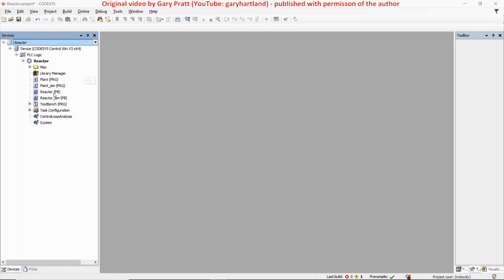In part 1 we showed the analog sensor object, which included a number of configurable inputs. In this part we will show how we add configuration inputs to the reusable object we built in part 2, and how this object connects to a central configuration service. It will also go through the features of this central service, which include the ability to create an editable CSV file containing the default values for all the configuration inputs of all the configurable objects, the ability to read this modified file at startup to properly configure all the configurable objects, and the ability to save individual configuration changes to allow tuning parameters to be captured and stored on the fly.